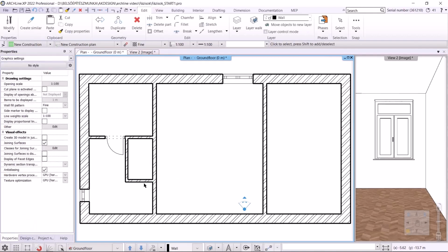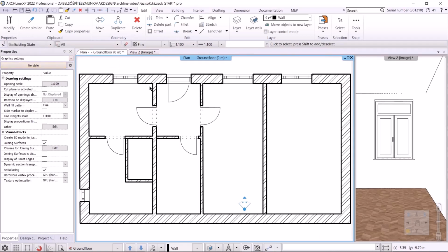In the next step, the new door and windows must be created. I will place the front doors and windows first. At the moment, it is not visible where the door and window that I designated for the demolition was. To make it visible, you have to switch to the All Phase filter. The existing items are now visible.